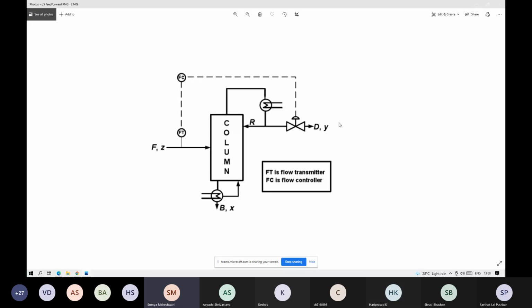Right. So the point I'm trying to make is that I understand the feedback and feed forward system here, and if we were to place the control valve somewhere where the column is getting the input, the B side, right? So B is the feed stream, B and X here. So maybe we could control the Y, the final composition Y of the output stream.